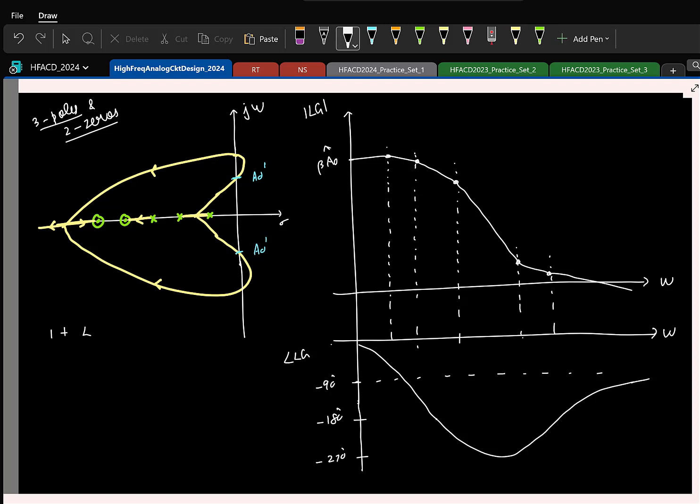So yeah, once again, this is the equation that we are trying to solve to get the closed loop poles. The roots of this can be a complex number, but for DC gain A naught prime, two of the poles are exactly on the j omega axis. There is no real portion. So which means even if I substitute s as some j omega, let's say some j omega naught, it will be 0, right?